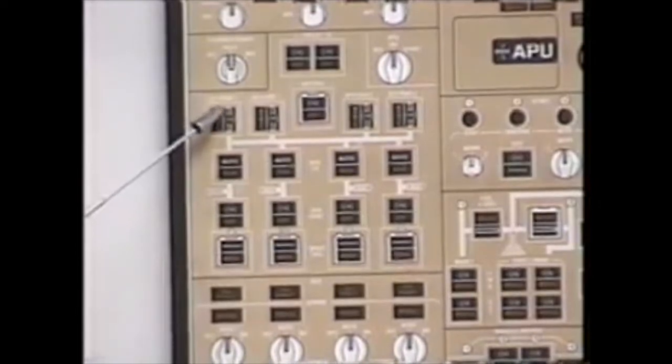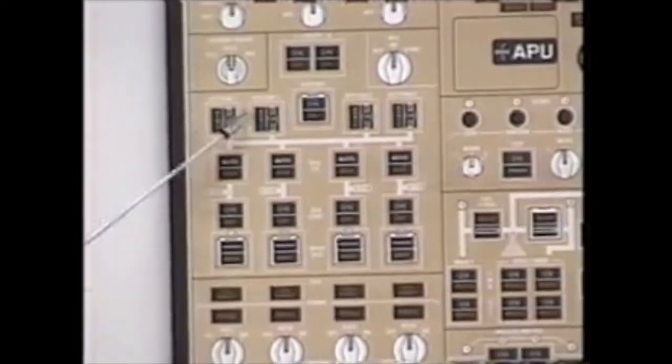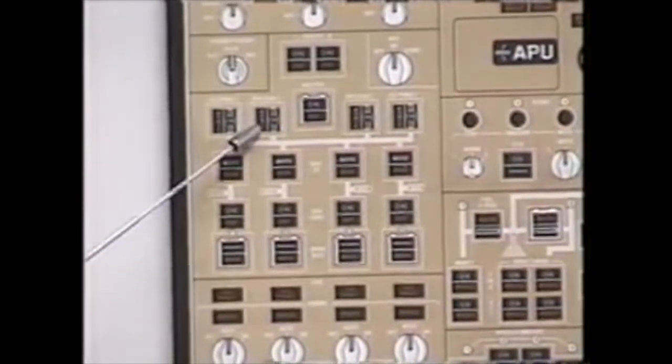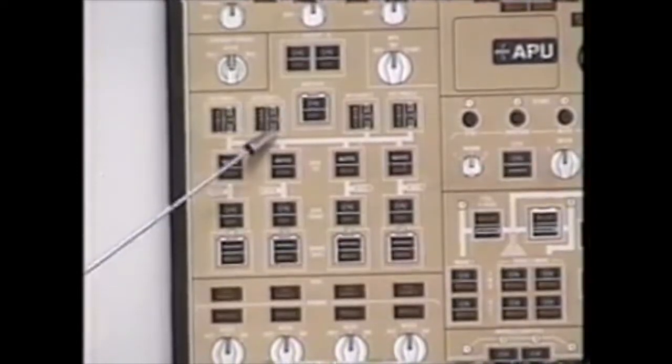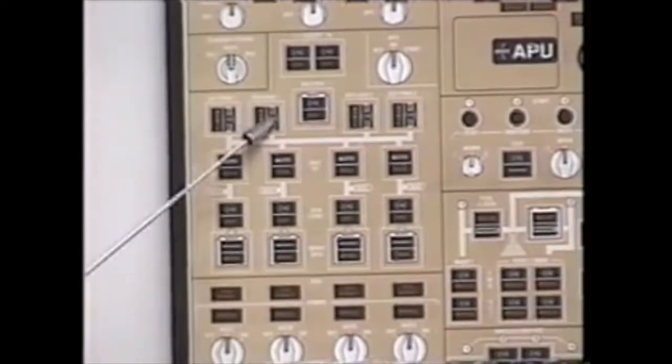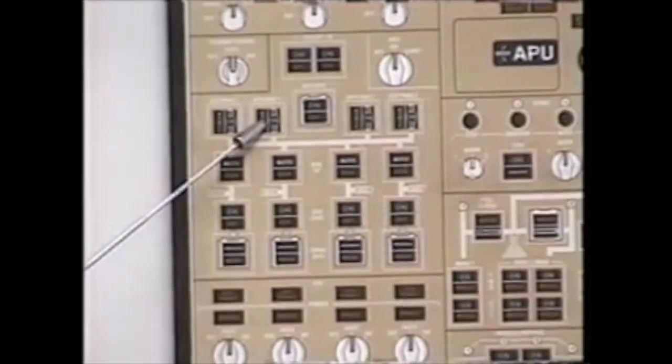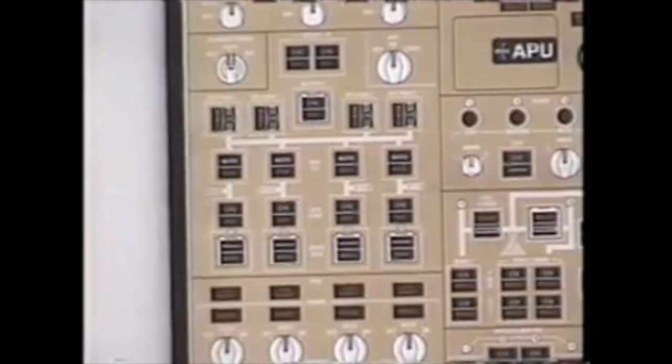If external power number 1 is not available, start your APU. As soon as the avail light comes on, the ground handling bus will be powered. You can place the generator online, powering your airplane. It will still power the ground handling bus. If there is no light in this switch or this switch, regardless of the other status of your airplane, the ground handling bus is not powered. It is impossible to power the ground handling bus from external power number 2 or APU generator number 2.